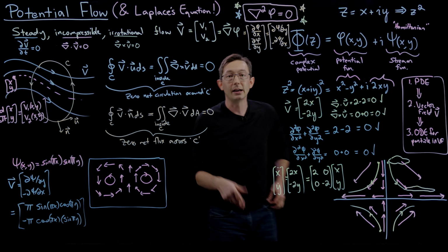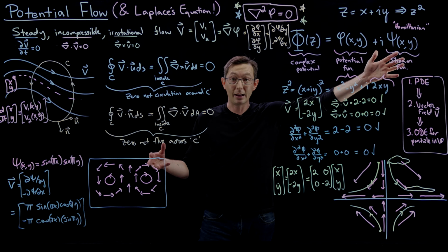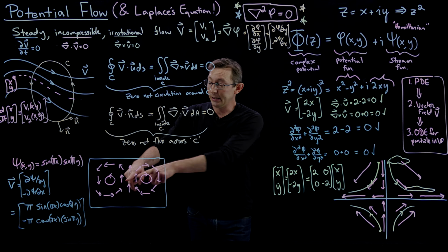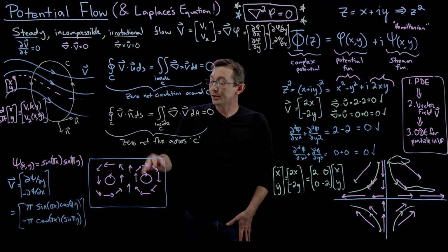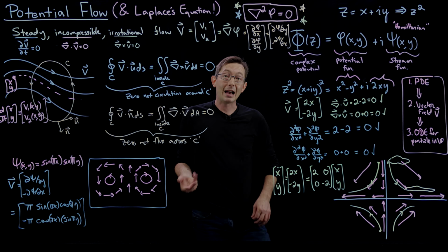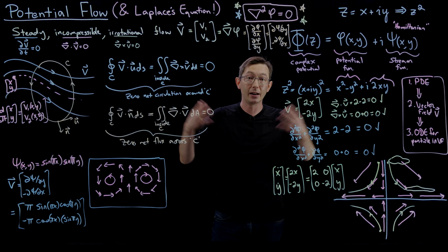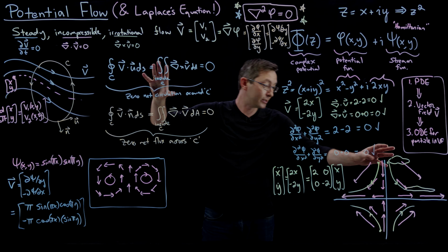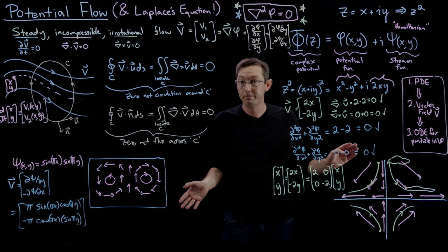And if you actually, in MATLAB or in Python, start plotting the streamlines, the level sets, or you start plotting this vector field established here, you'll see that this actually creates this counter-rotating ocean gyre. And this is something I often code up with my class, and we'll start dropping particles. We'll see where they start stretching and mixing, and we'll actually compute these quantities, drop a blob of particles and see how they stretch and fold.